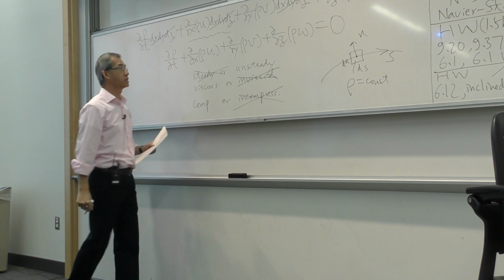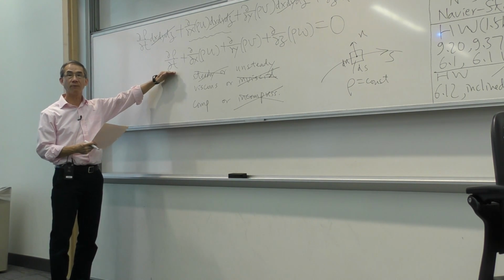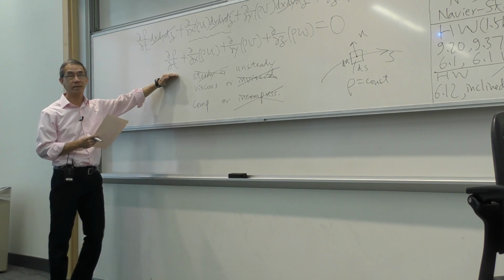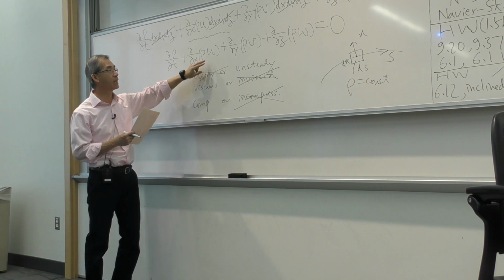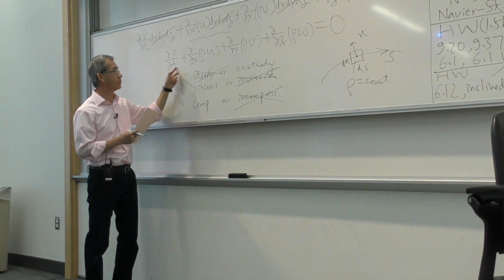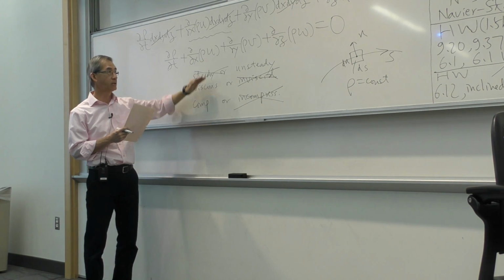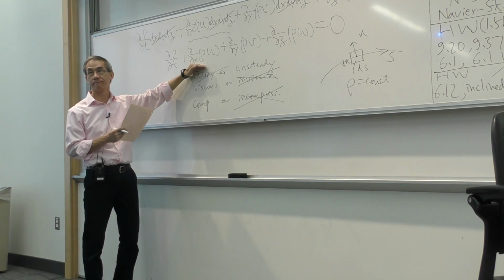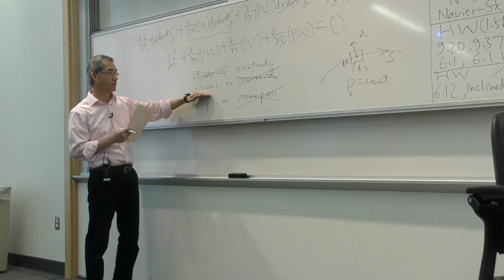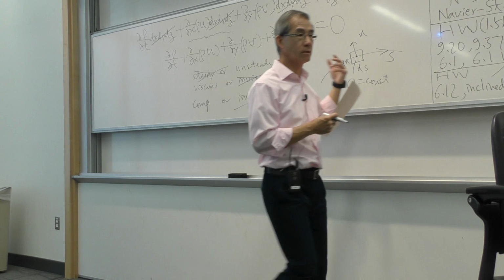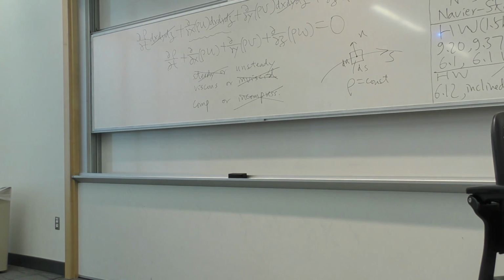And hence this general equation will allow us to deal with changing density flow. And that is accounted for with the derivative of density inside those brackets for both steady or otherwise unsteady continuity. So the answer to that trick question is, this equation is good for everything, anything. Unsteady, viscous, changing density flow. So this, in a way, is good for any fluid problem. Right? Do you understand that?